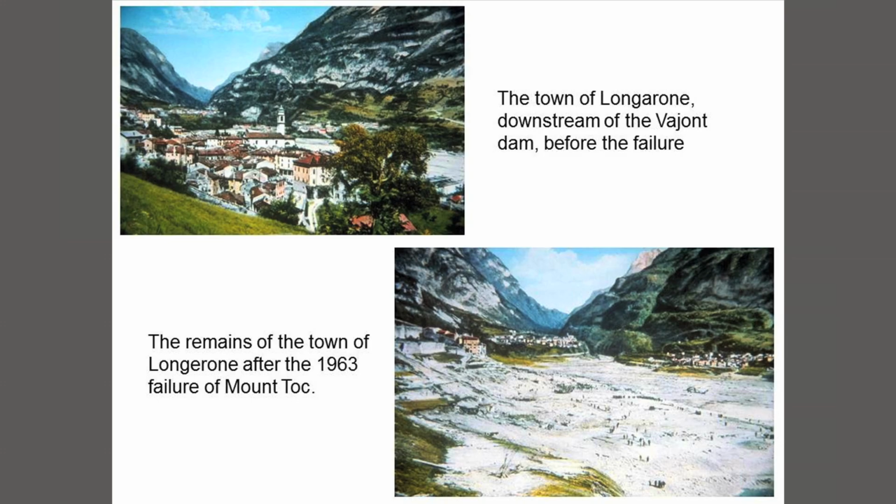In the mining field, a lot of coal mining, for example, was done by room and pillar mining, where the coal seam, which would be horizontal, is extracted by removing a cross pattern of tunnels, leaving a pillar at each intersection. And the tendency is to rob those pillars because that's a valuable resource you're leaving in place. And in many cases, the estimates were wrong and the pillars failed.